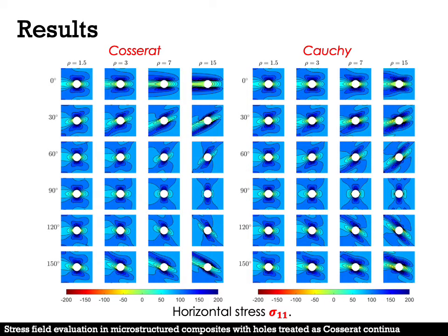That is the result of the horizontal stress sigma 11. We can see that the distribution of sigma 11 shows a very clear direction effect with respect to beta. However, the direction effect is less evident for the shorter blocks when rho equals 1.5. As rho increases, sigma 11 is more evident and the high stress area becomes wider, except for the 19 degree.